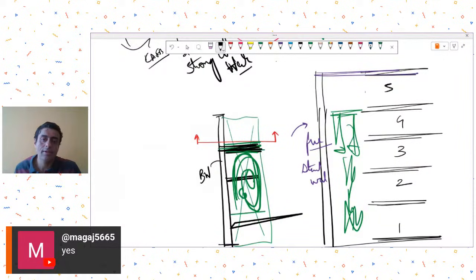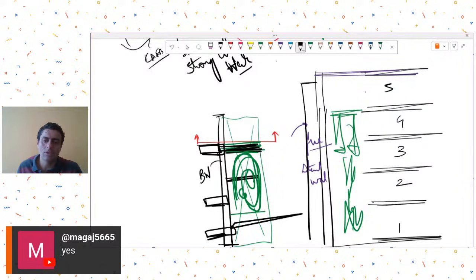Let's assume that for 5 levels you're not getting a tie, then it's a problem. Then you may have to introduce counterforts. So try introducing counterforts over here. Those counterforts will have to support your 5 levels, and whatever is the lateral pressure acting from outside, those counterforts will provide resistance against it.